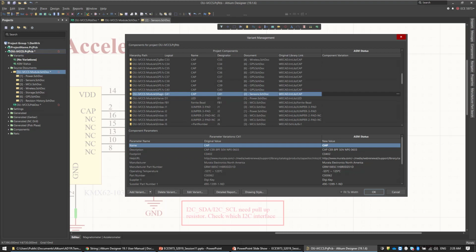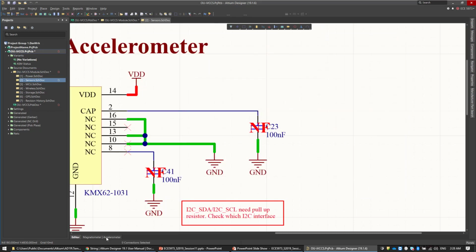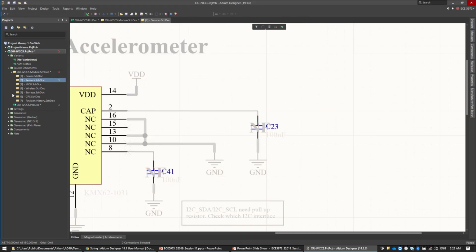Basically, I click on it and I get this list. So variation kind: you need this component to be fitted in this variation called assembly status, or not fitted, or alternate part. So if I specify this as not fitted, click on it, and now this component, when I select assembly status in here, click on it. Now let's take a look. When I select assembly status, you will see how this X comes over.